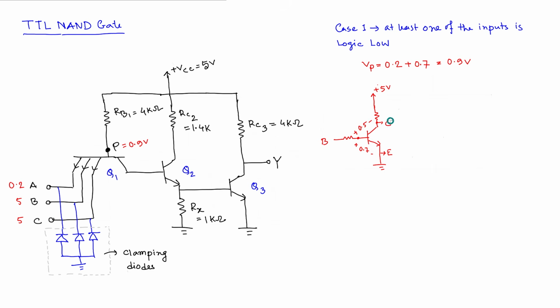Okay, so if collector can be 0.5 volt lower than base, that will be enough to make this particular junction forward biased. But if we look at this junction from base to emitter, this was 0.7. So why this difference? I mean, both of them are similar kind of junctions, similar kind of like your diodes, but still the voltage required is different. The reason for that I explained was because of the way they are doped. The emitter is highly doped, but collector is not highly doped. As a result, the voltage required for being forward biased was not the same, right?